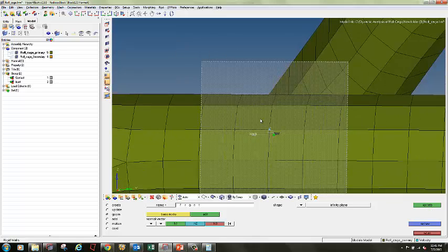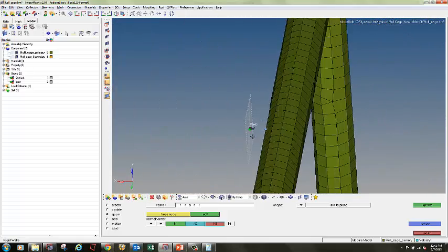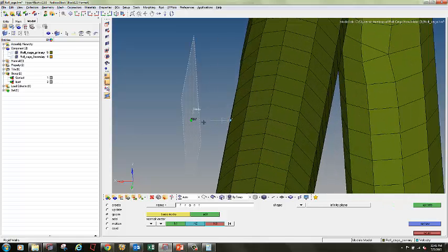So you can see I have created a rigid wall. This is of 10 by 10 and you can see the direction here. This is the most important thing. If this direction is opposite, then the contact will not happen, so the impact will not happen. It has to be in the opposite direction of the force, or sorry, velocity.